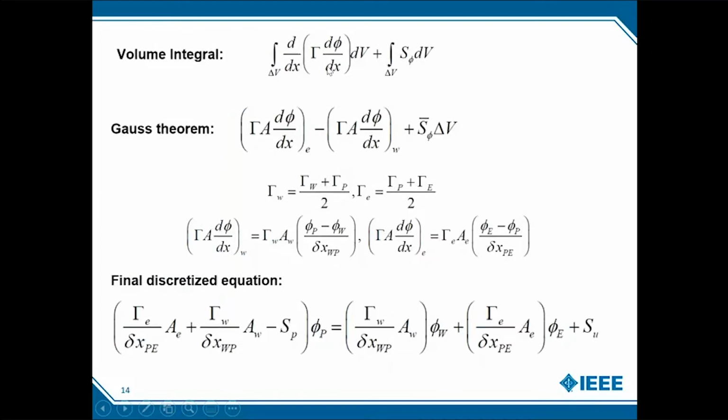That is why we have e minus w. So basically what we did from this step to this step is convert the control volume integral into a control surface, into an area integral. That's it. And over here, Sv into delta v, Sv is just a source term, a constant which has come out, and dV just changes to delta V. So now we have this particular equation.